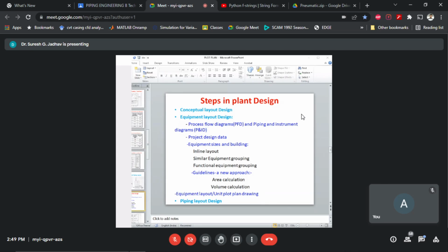Reactors are arranged in a row, which need a crane or trolley for removing equipment internals and for material handling equipment. Equipment containing acid or toxic material is grouped and located within a curb area which will have the facility to drain out the effluent to the treatment plant or for neutralizing it.